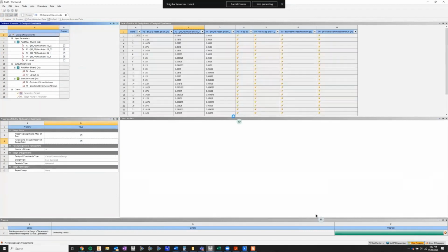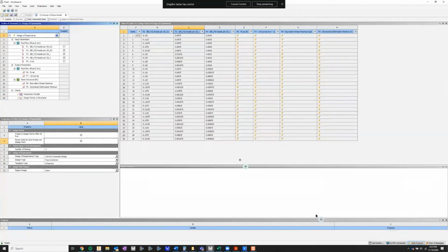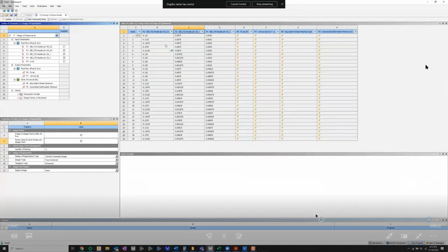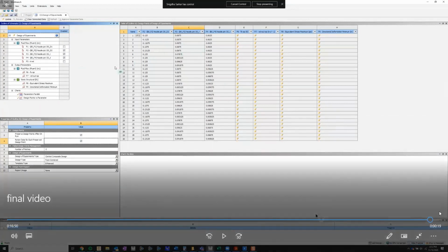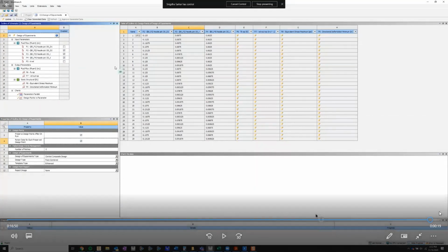So once you set up your DOE, what Design Explorer does is it automatically comes up with all the design points that you would need to fill up your design space. What that means is these are the minimum recommended number of design point entries that you would require to establish a relationship or trends between your input parameters and output parameters.